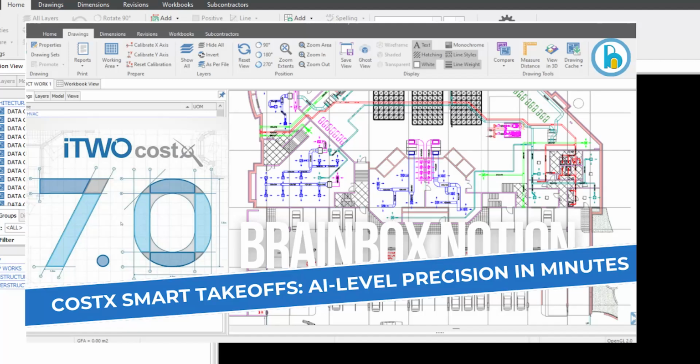I'm Yusuf Musa Uba. In today's video, we'll be exploring a game-changing feature in CostX, which is Smart Takeoff. This feature leverages AI-level precision to streamline your quantity takeoff processes, helping you to achieve accurate results in a fraction of the time. If you are tired of tedious manual measurement, this tutorial is for you. I will guide you through how to use Smart Takeoff to identify, measure, and quantify elements with just a few clicks. You will learn how to set up your dimension group, adjust your variation, and apply logical, mathematical, and string functions to boost your efficiency.